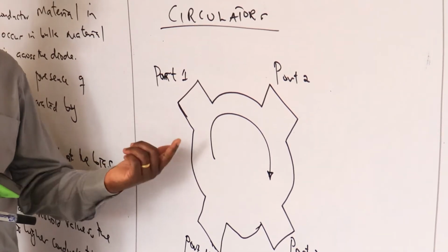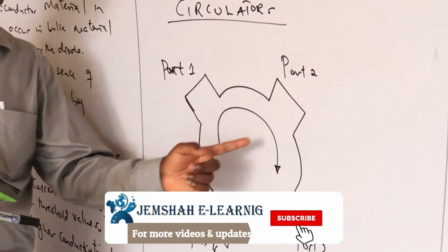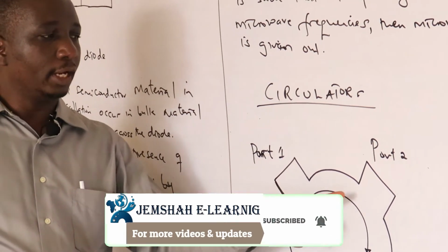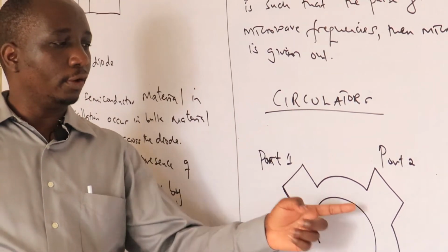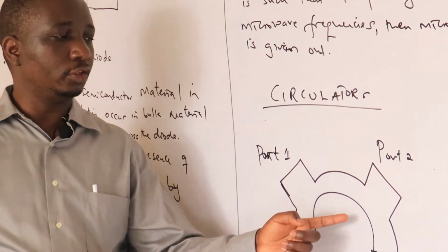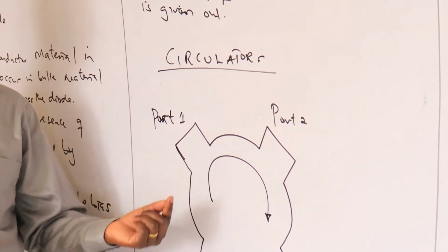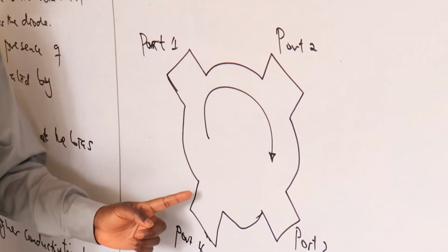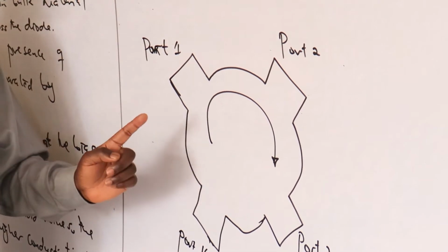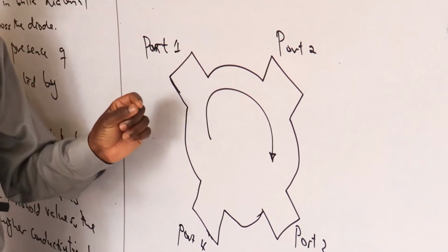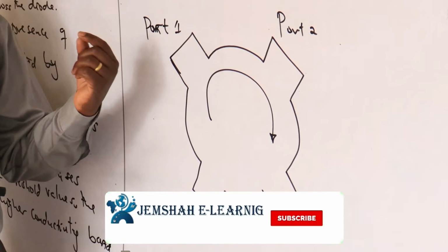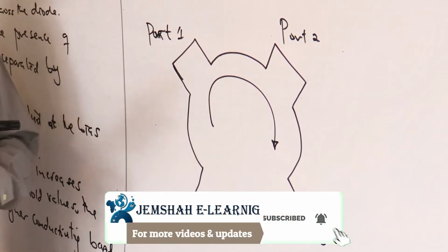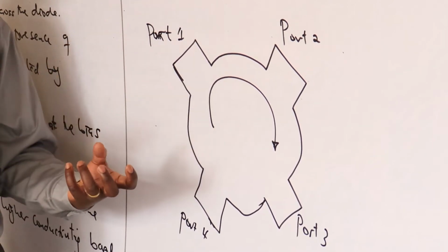But when it gets to port 2, which the equipment or the frequency is not tuned to, then at port 2 the transmission mode is changed so that the signal doesn't come out through port 2. The same applies to port 3 and port 1. The only time the signal will be coupled out is when the port at which it is tuned is able to match the transmission mode. The port which is not tuned changes the transmission mode so that it creates a high impedance path.